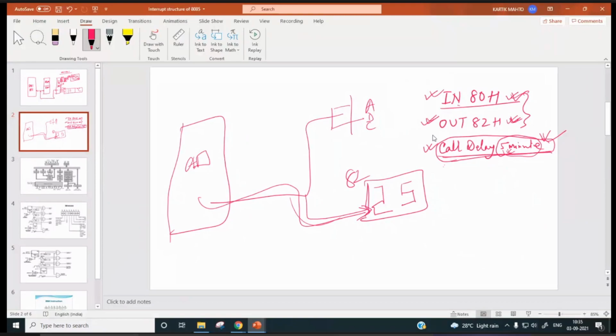So you will write an unconditional jump instruction, JMP LOOP. The processor will keep inputting data from port A0H and keep displaying the inputted data at port 82H every 5 minutes. So this will be our program.